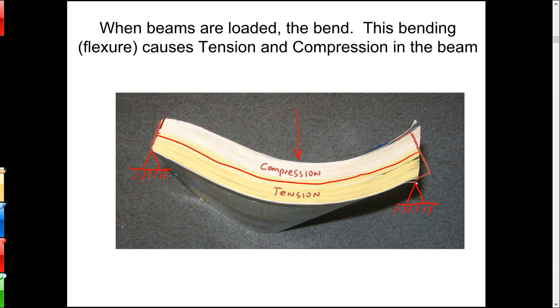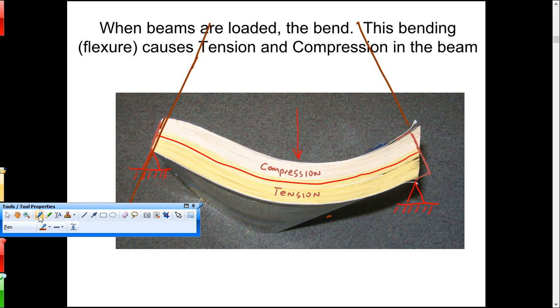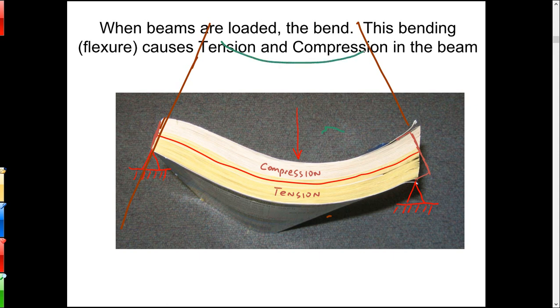The reason is, when you have this circular bending, or whatever kind of curve that is, as you get further and further away, you get a bigger and bigger sector of the circle, a bigger distance to traverse as you hold that given angle of bending, okay? So what's happening here is there's a given angle of bending here, and we could call that whatever you want, theta. To keep that constant theta, this distance that I'm outlining on the bottom has to be longer than the one on the top, right?